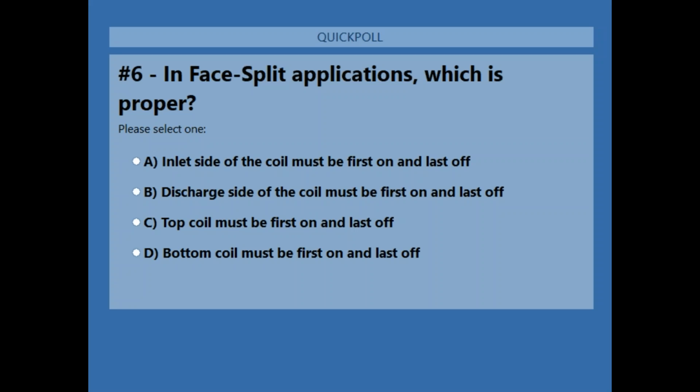Weigh-in charge is another way of doing it, because we can't get the machine fully loaded, and it's the only way you can use a superheat chart on a fixed metering device or a subcooling chart on a variable position metering device. The only way you get it on chart and use the chart is at a full load, 100% full load. A lot of rambling there. I hope that makes sense.